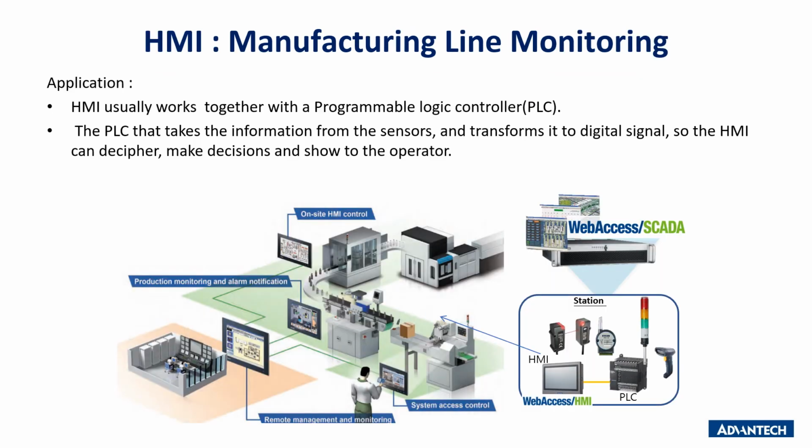This is an application of a manufacturing line monitoring system, which allows the operators to monitor everything on the factory from a centralized room. The Industry 4.0 solution enables operators to acquire data at different stages and stations of production. In this application, every station contains different sensors such as switches, light towers, and analog signals.